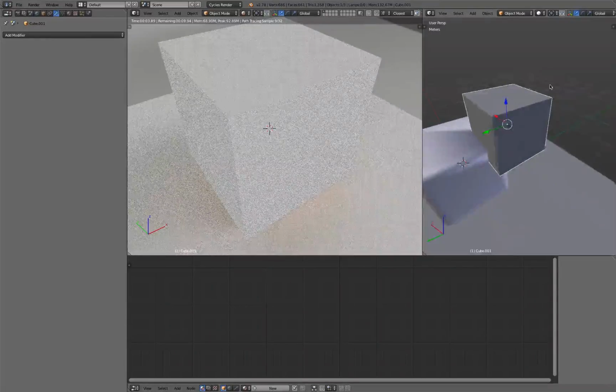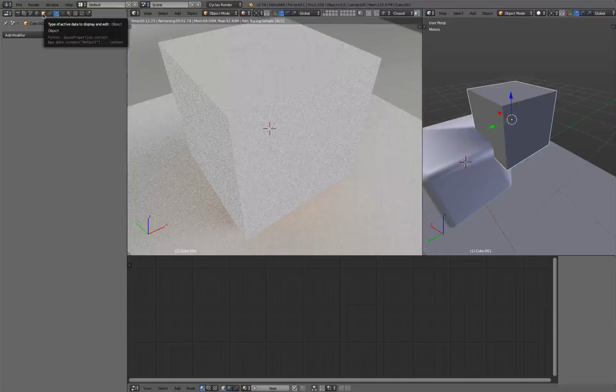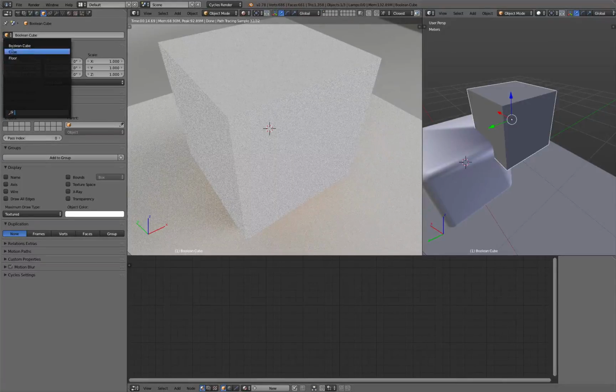and then we select this cube to cut this piece out. And then this cube you see actually in the rendering is in my way. So two ways to fix this. This is, for example, a Boolean cube. So we can call this one cube Boolean, or sometimes what I do very often, I mark all objects that do Boolean functions with Boolean, and then I use the name, because then later it's very easy to filter all the Boolean objects out.